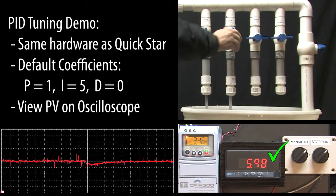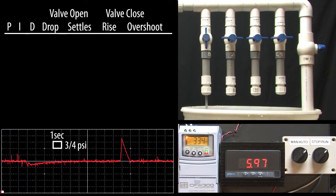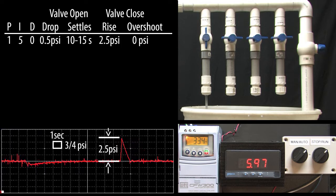I'll close the valve quickly, and we see the abrupt pressure increase, and then it slowly settles out back at 6 psi over 10 to 15 seconds. Each of these divisions is 3/4 of a psi, so it looks like the pressure dropped maybe half a psi when we open a valve and rose 2.5 psi when we close the valve abruptly, which makes sense. Opening a valve just relaxes things. Closing a valve quickly creates a very sudden change in the process, so you get that big jump in pressure.